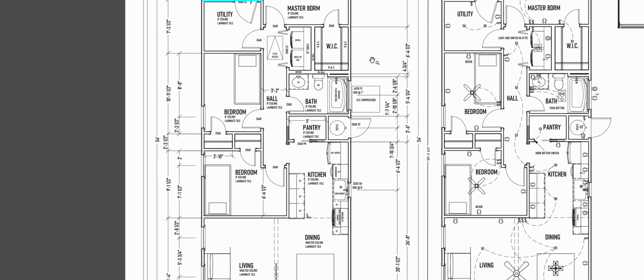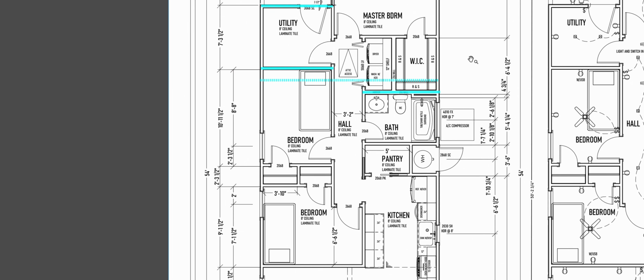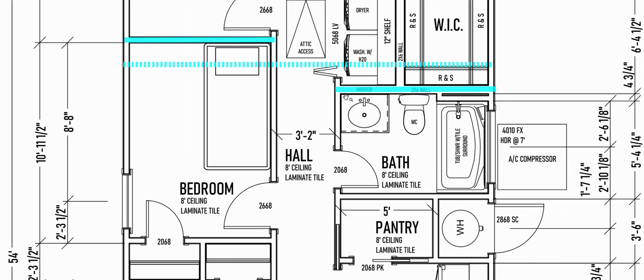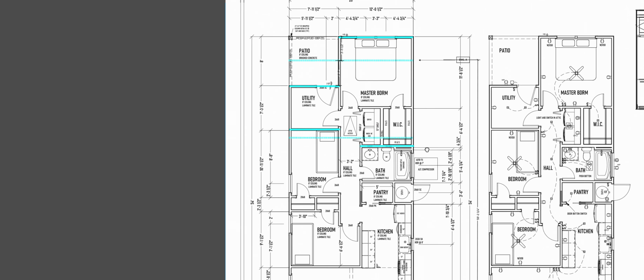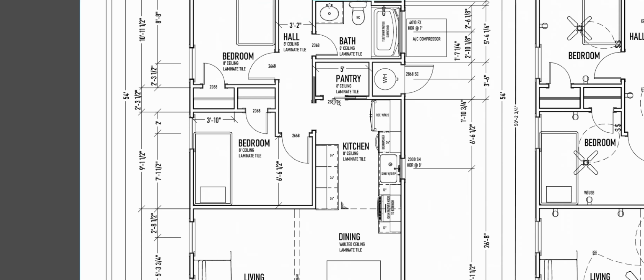And we're going to have this braced wall line. Now, the walls don't have to be touching each other and connected for me to claim this as a braced wall line. As long as I follow the rule of I got a panel that's somewhere within 10 feet of the beginning and 10 feet of the end, and I don't go more than 20 feet along my line without having a panel. All right, so there's another one.